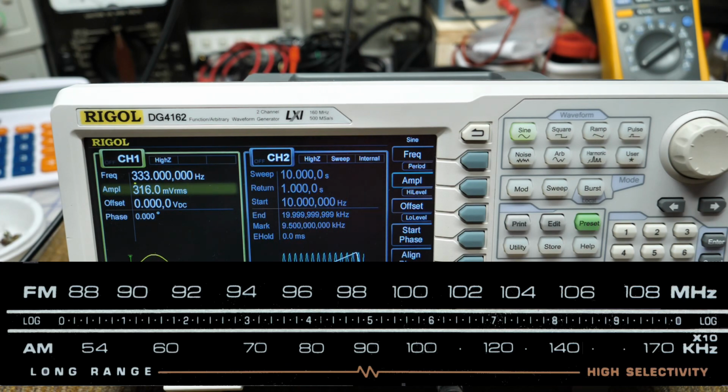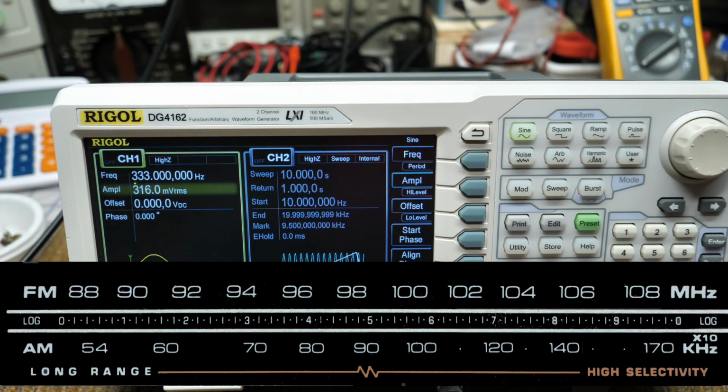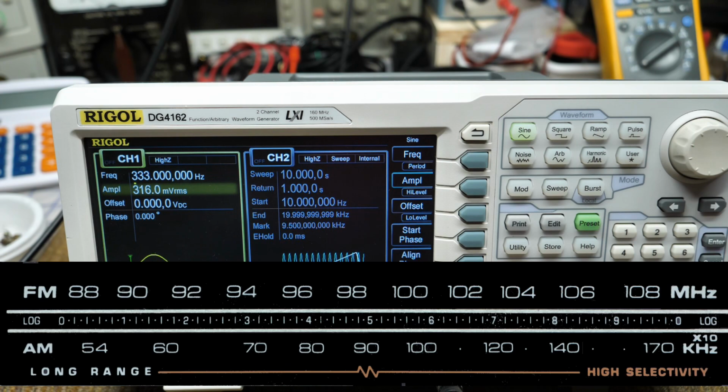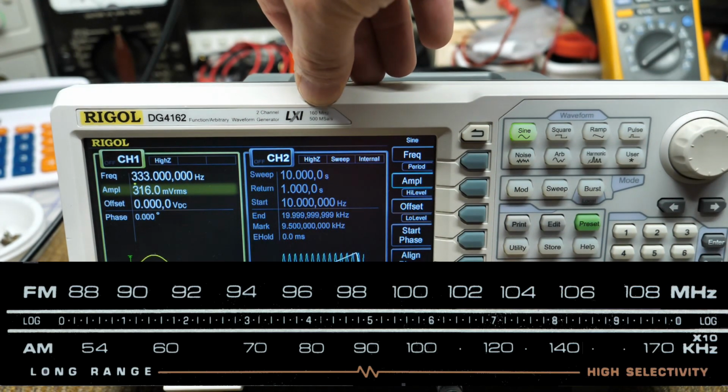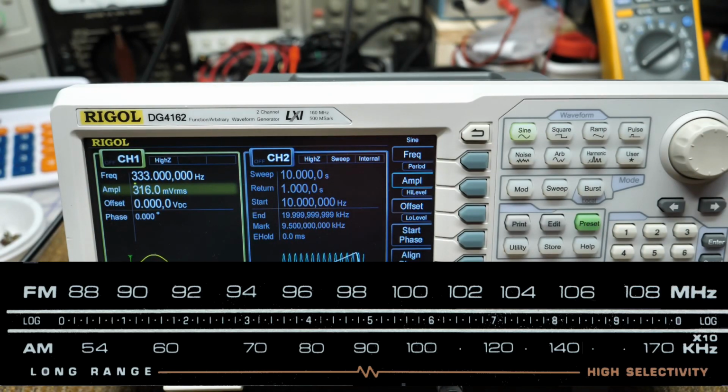Now when you look at an FM radio, FM broadcast starts at around 88 megahertz, or about 87.5, something like that, okay? Megahertz. And it tops out at 108 megahertz. So in order to get the entire frequency band, generate any frequency within an FM radio's capabilities, you have to have a signal generator that can output up to 108 megahertz. Since this one will go up to 160 megahertz, you're good.